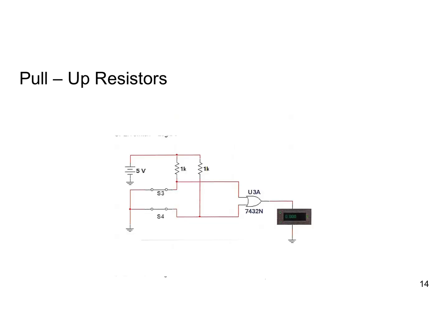Okay, pull-up resistors. Again, it's application dependent. In this case, we have pull-up resistors so that when the switch is closed, we have a direct path to the ground. So in that case, that input is going to be 0, and this input is going to be 0.